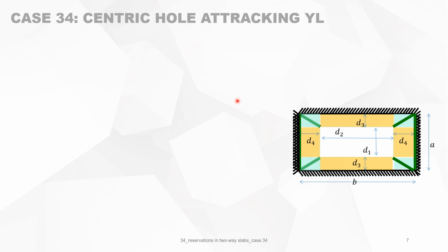We can calculate now the work done by the external forces. It is equal to, when we look at the triangle shaped surfaces in the green location, then we see that when we got D4 times D3 for this total, it comprises of triangles, so the mean deflection is delta over 3. And we got that 1, 2, 3, 4 times, which is this amount.